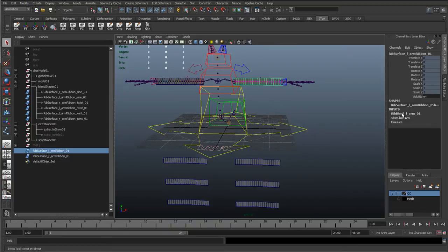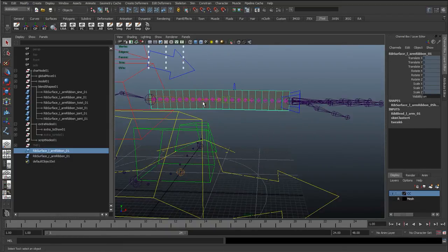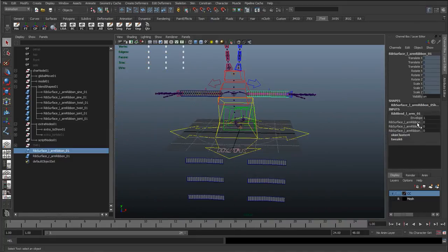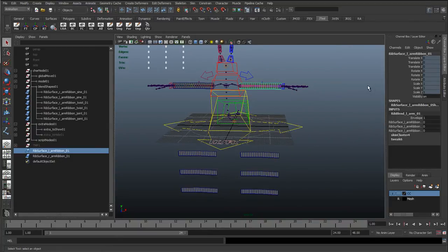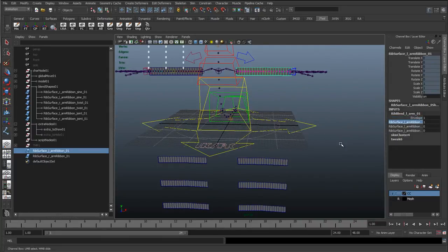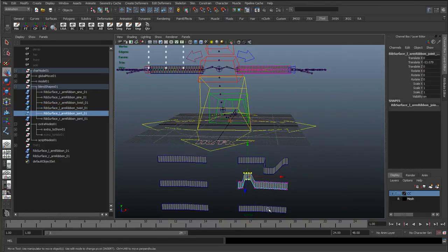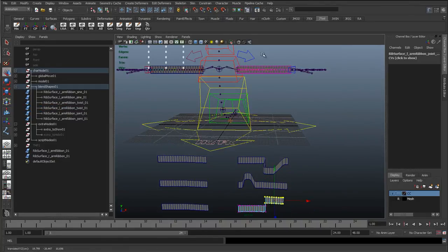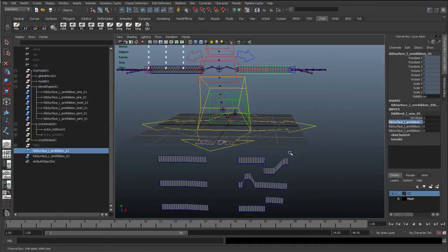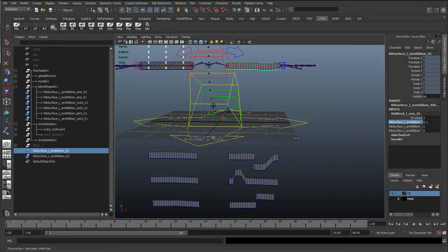And what you can see in here, we now have the skin cluster, which is skinned to these arm joints, and we have the blend shape. If we click the blend shape, you can see you've got 3 different blend shapes here. So it's similar to the constraints. You have a weight value, and basically this means from 0 to 1 we're going to match these down here. So just to test this, what we could do is shift these about and blend into a value of 1. We can see it's going to match the edits we've done below.